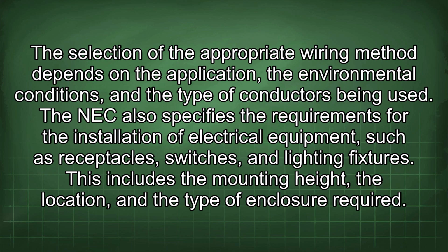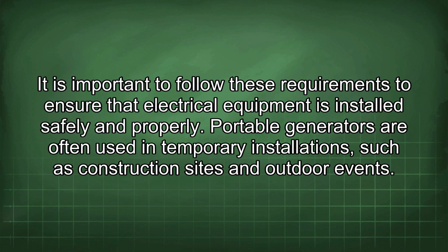The NEC also specifies the requirements for the installation of electrical equipment, such as receptacles, switches, and lighting fixtures. This includes the mounting height, the location, and the type of enclosure required. It is important to follow these requirements to ensure that electrical equipment is installed safely and properly.